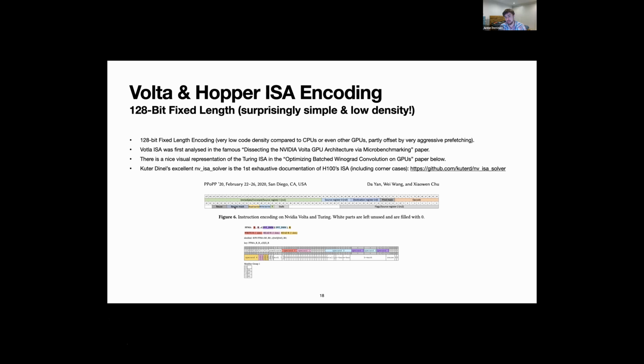The instruction itself will encode the way the dependencies work. So there's still a bit of hardware for tracking things, but it's a lot less. And all of the long dependency instructions will have a write barrier, which is when the data for like a load comes back, and a read barrier, which might be when the address register where the address is stored for the load is freed up. So that happens much earlier than the actual data coming back.